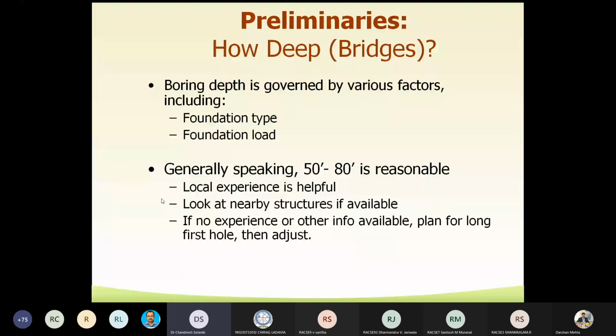How deep will you go? Boring depth is governed by various factors, including foundation type, foundation loads, and so on. Generally speaking, as far as the depth of exploration for bridges is concerned, 50 feet to 80 feet is reasonable in the case of normal bridges. However, local experience is useful. If you are familiar with this particular site, it may reduce your depth of exploration.